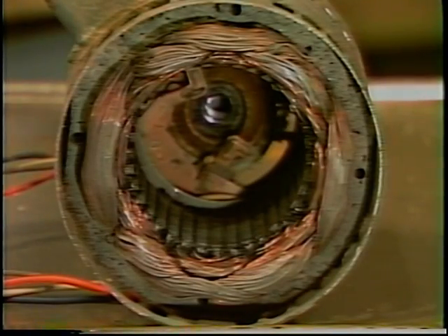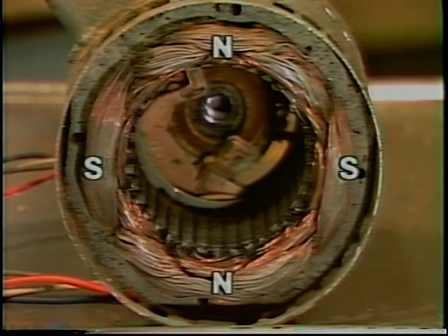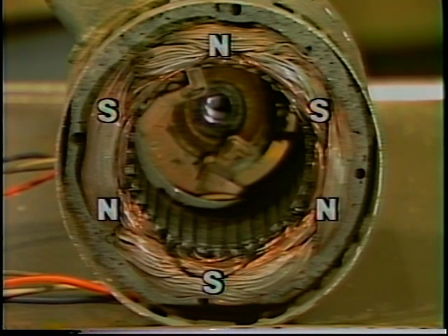An AC motor which can run at more than one fixed speed makes use of this principle. When you set it to run on a different speed, the switch connects the individual windings in the motor for a different number of poles. For maximum speed, the motor is connected for the fewest number of poles. Reconnecting the windings for twice as many poles cuts the speed in half. Three times as many poles produce one-third the speed, and so on.